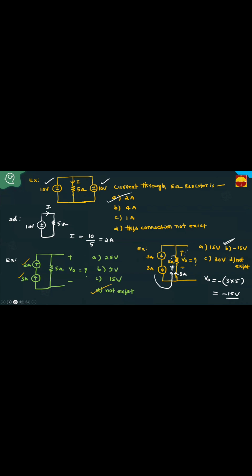These are the observations with respect to voltage sources. Here I am giving 2 more points. First one: a current source in series with a resistance. Like this is the R1 resistance, and this is the load. If the current source is I, the current through R1 is also I, and after R1 is also I. There is no drop in the current. Current remains the same. That is, a resistance in series with the ideal current source is neglected. But this R1 is considered only in power calculation.